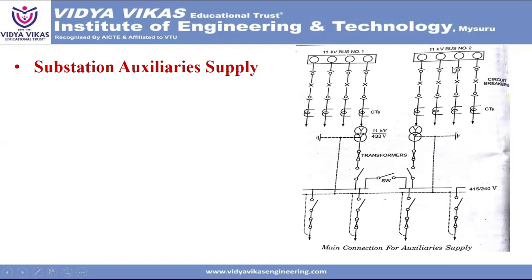So 11 kV bus bar 1, 11 kV bus bar 2. Here we need to connect an isolator, a circuit breaker, isolator, CT, and then a transformer, 11 kV/433 volt transformer, and from here to the auxiliary supply.